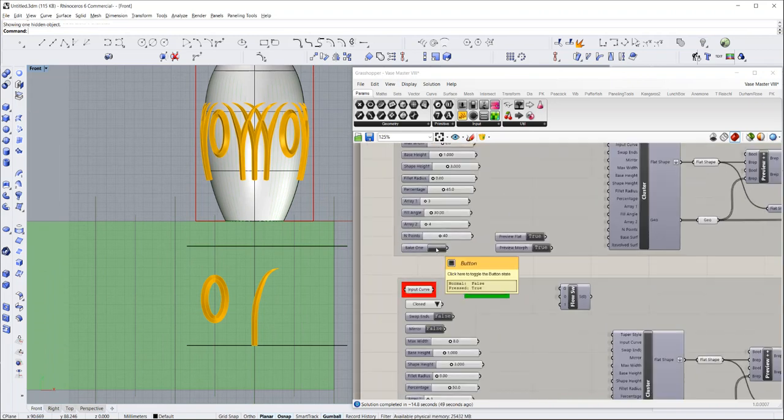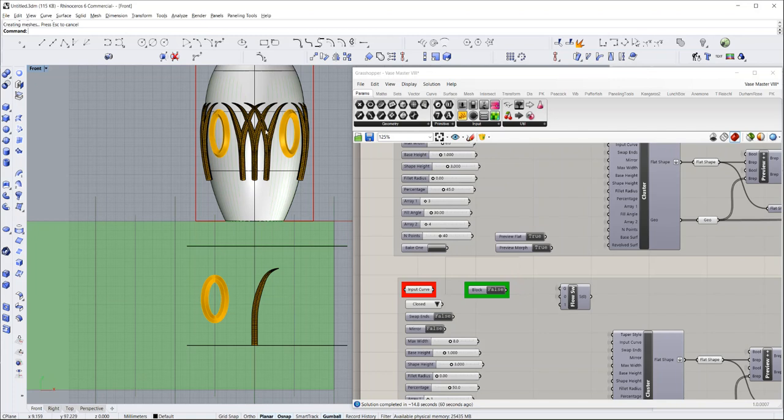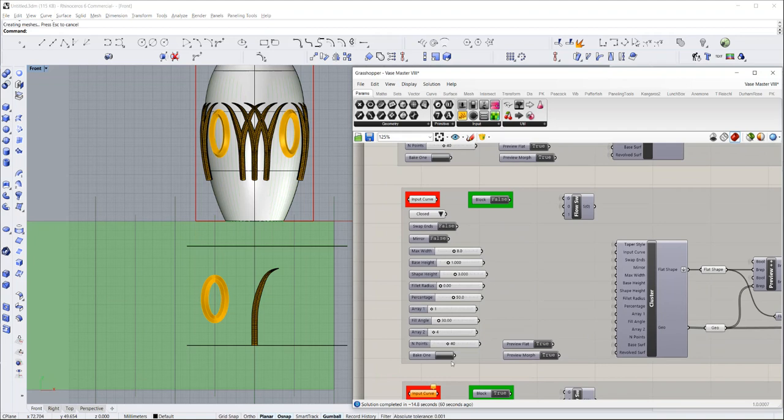And now we need to bake our items. Single click on these items. Do not double click or you'll get double, triple, quadruple items. There's a difference between Boolean and button. This happens to be a button. This is a Boolean. So single click on it and you see it turn light gray. Sometimes that'll take a while. And we now see our items appear with their ISO curves. And all we need to do is the same thing on this one. And we now have those baked.